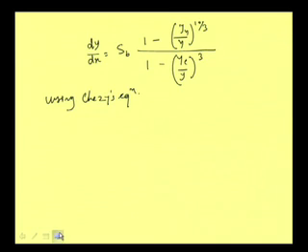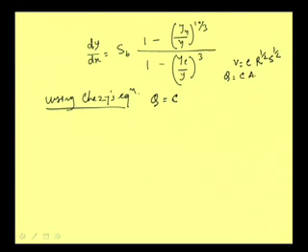Now, if we write Chezy's equation, then we can write, say, Q is equal to C, we remember that in Chezy's formula V is equal to C root over RS, that means R to the power half, then S to the power half, and Q is equal to C into area, so V into area basically. So, this part is velocity, so we are writing this velocity in this form, and then we are multiplying this by area, keeping the resistance parameter term separately and other terms related to the shape and the bed slope separately. Well, so we can write like that.